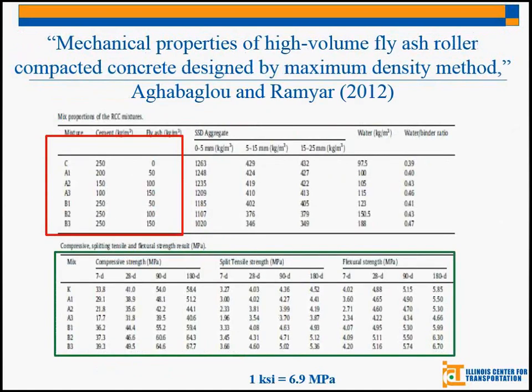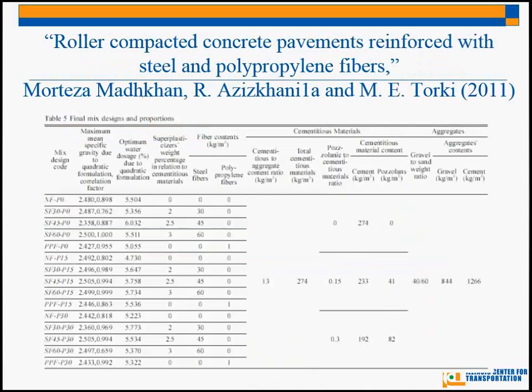And this is, again, reiterating that fact, but this has a slightly lower cement content. We're getting more down into the range of what is typical RCC, and a lot of the strengths, the compressive, split tensile, and flexural strength, showed similar results to typical concrete.